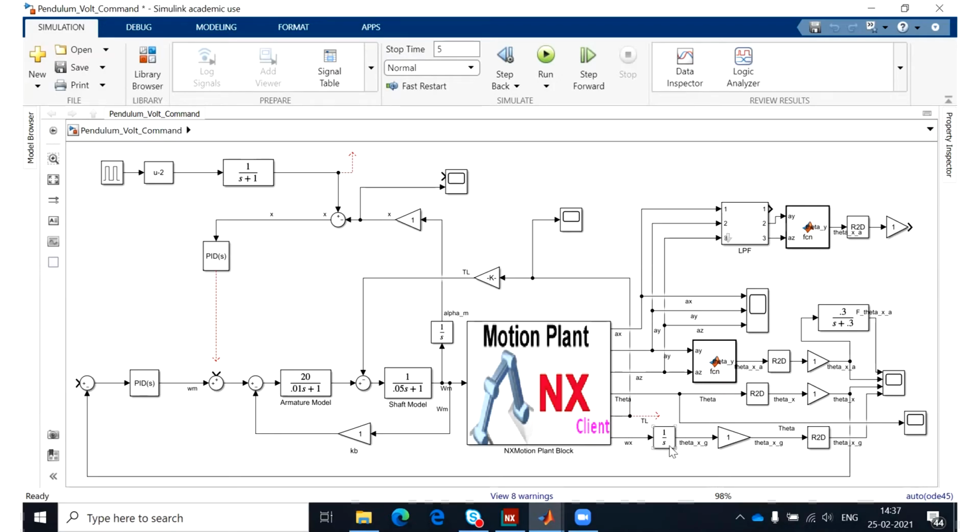So okay, we have it here, and this omega x is basically what you get from the gyro, and later you can integrate that. Integration in Simulink would be just a simple 1/s, and then of course you need to change the unit from radians to degrees if you're interested in having it in degrees, and then here you'll get the angle of the pendulum in degrees.